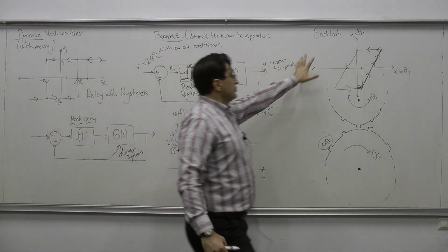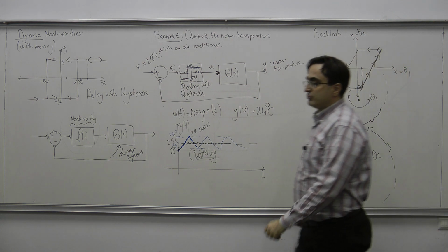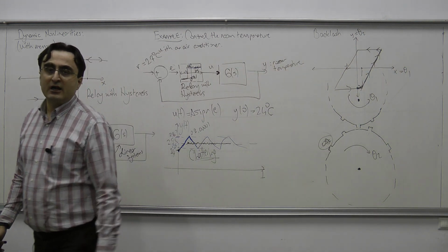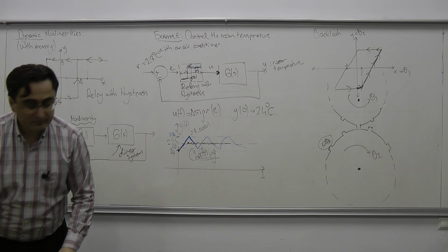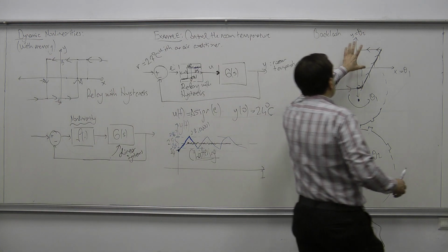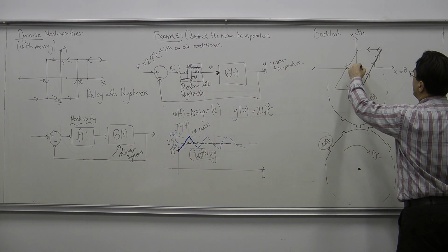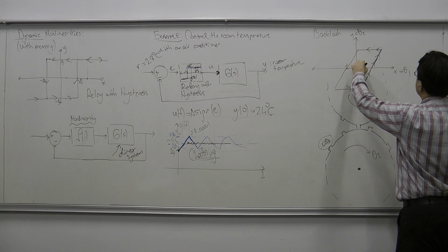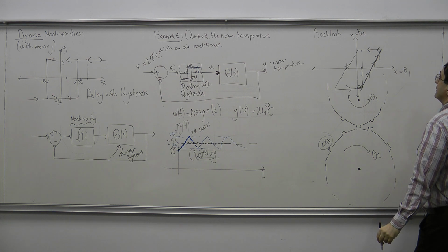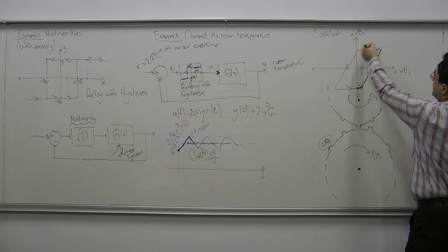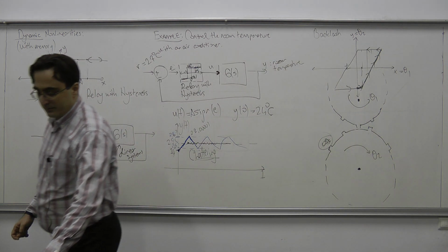And we can use a backlash model, if we have gears that would work like this, to model that type of behavior in our mathematical system. All right? So this is also, of course, a dynamic nonlinearity, because you see that for some theta 1 values, for some x values, it might take two different values. Okay? So this is also a dynamic element that is with memory. All right?